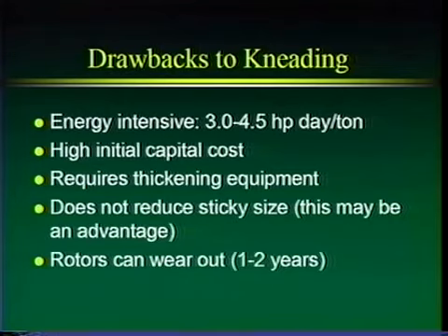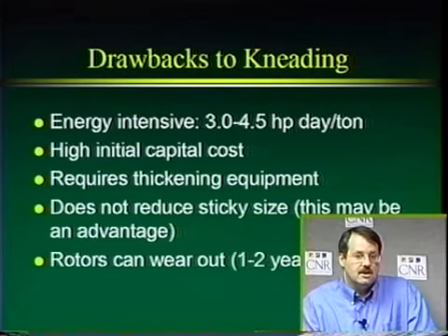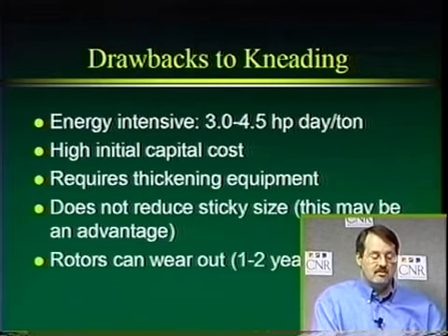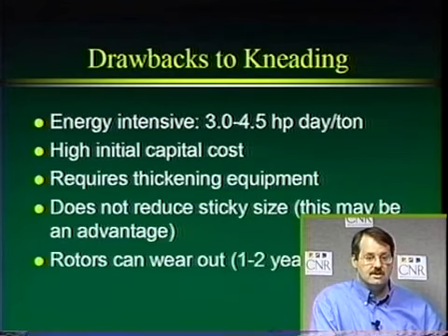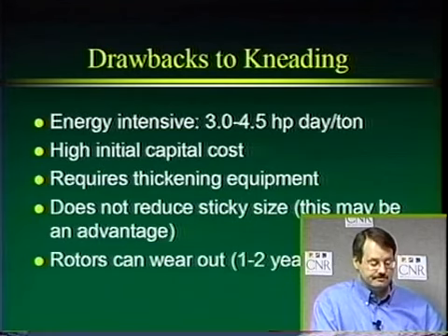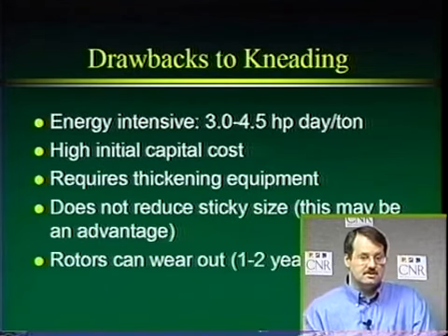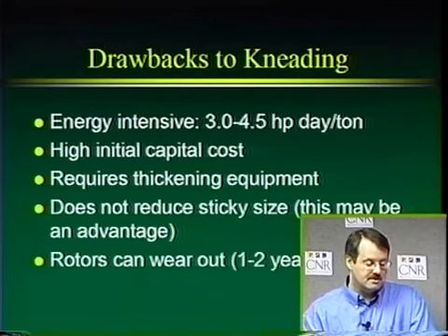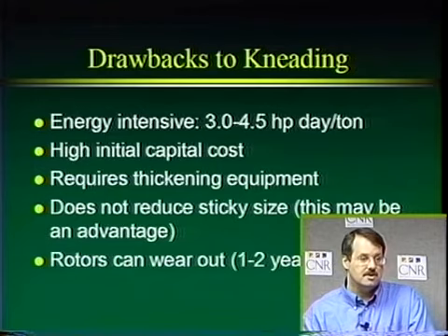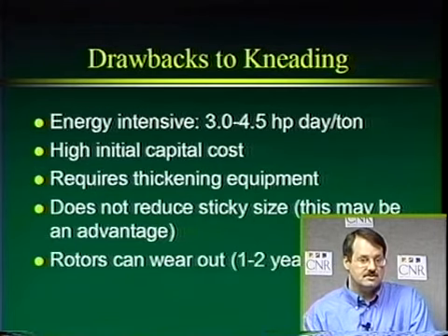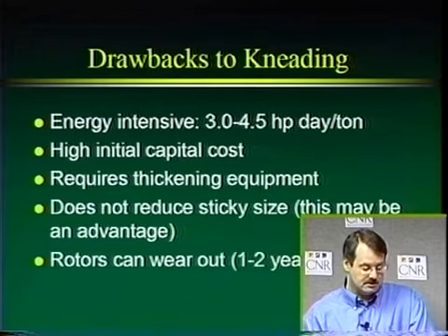And then the rotors can wear out. Every 1 or 2 years you have to replace your rotors, your teeth, because of all that shear action and the abrasive material that's in the pulp. That can be expensive. Disc dispersers, you also have to replace those discs, but the discs aren't as expensive, though they may wear out a little bit faster because of the faster speeds and the closer clearances of the teeth.